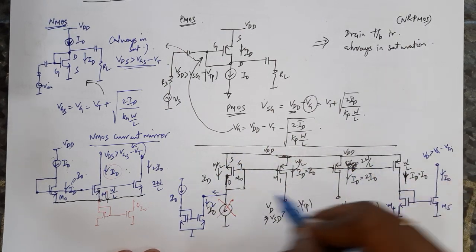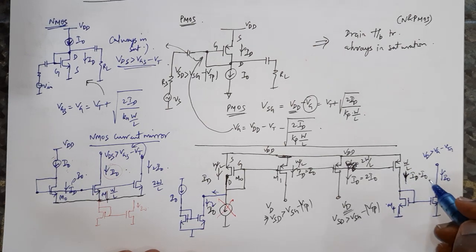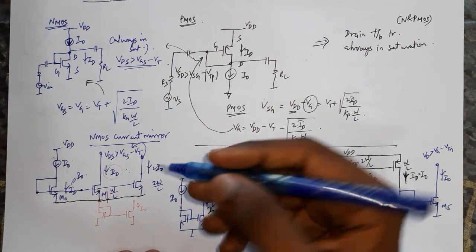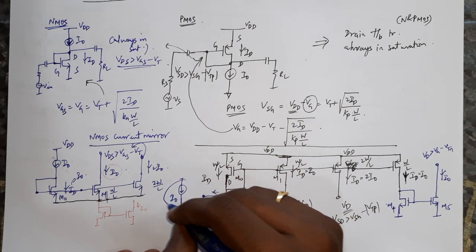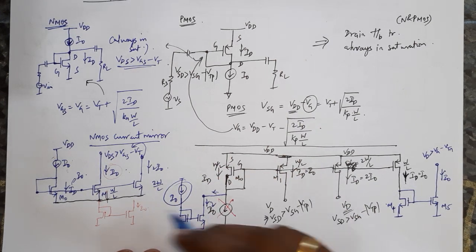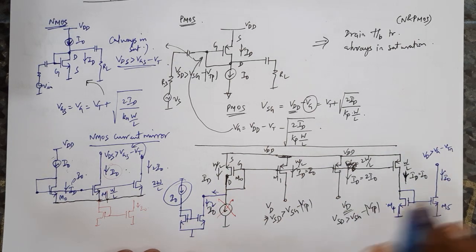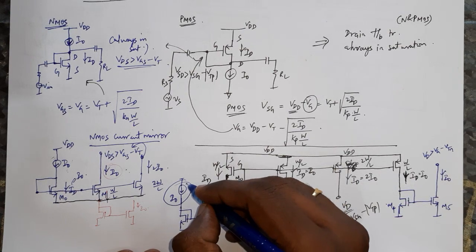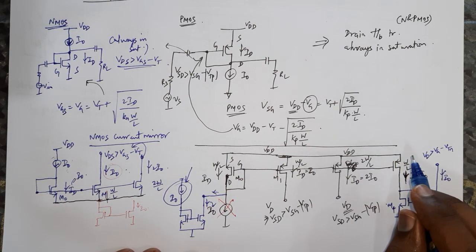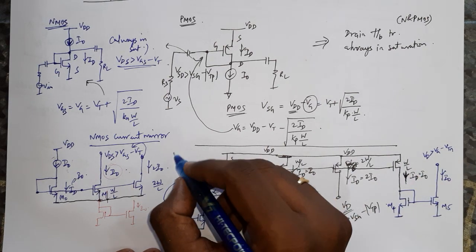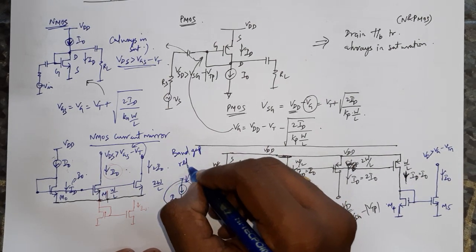So that is how you use the NMOS current mirror as a reference current source for the PMOS current mirror, and use the PMOS current mirror as a reference current source for the NMOS current mirror. But obviously by now you will have this very obvious question: first of all you need at least one I0 to generate any of the currents, but once you have this I0, any more copies of current can be created. But how to generate this I0 is a real question, which we will not be explaining in this course, but it can always be done through some kind of band gap reference circuits.